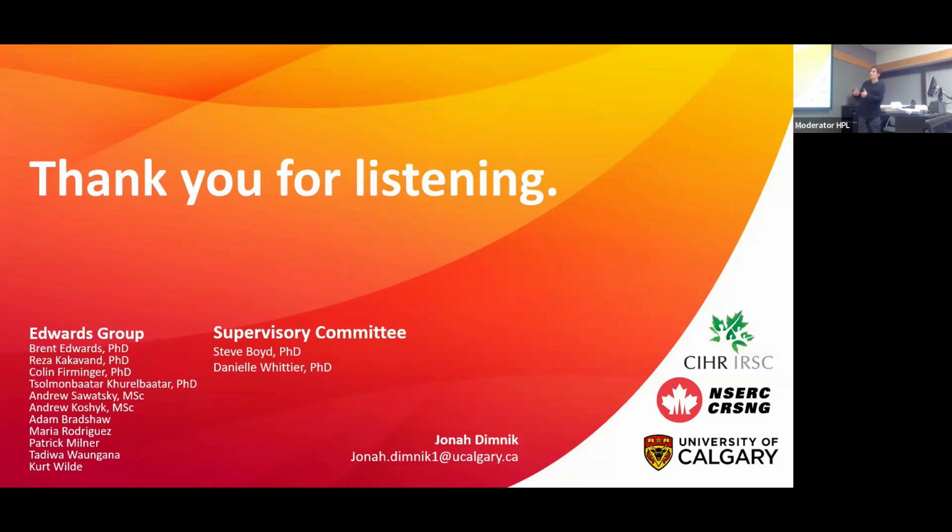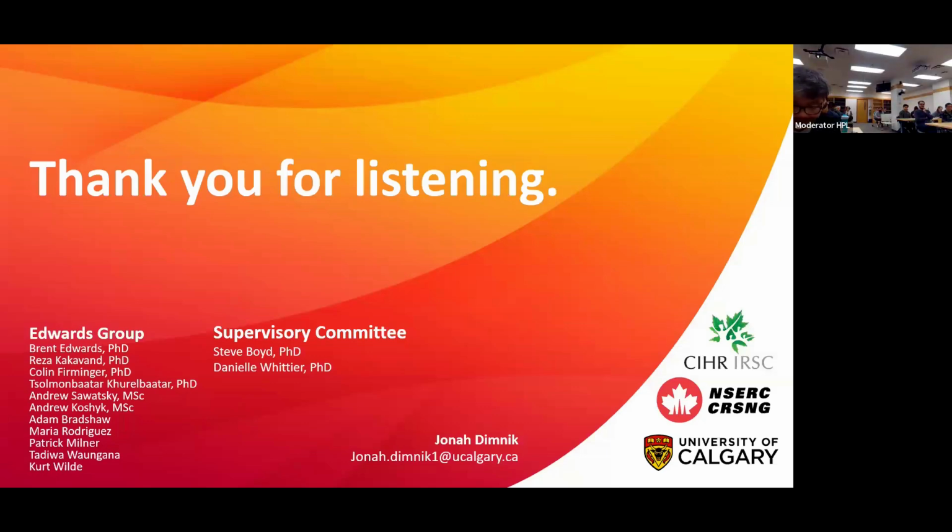And that's important for us because we're using this in FE models. People will use density-elasticity relationships for other research studies, for other purposes. And typically when they develop those relationships for human bone, they'll take a small machined sample and actually do a density measurement of the bone. So they'll maybe take the ash fraction and get the true density of the bone, and then they can measure out the elastic modulus through a mechanical test. So that's how they develop those relationships. They take a bunch of machined samples, measure the density, and get the elastic modulus from the mechanical test. They do destructive testing, and they can develop those curves.